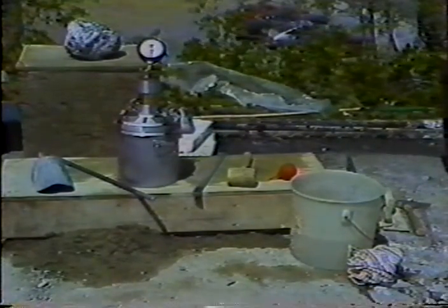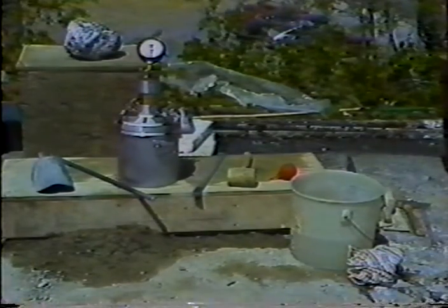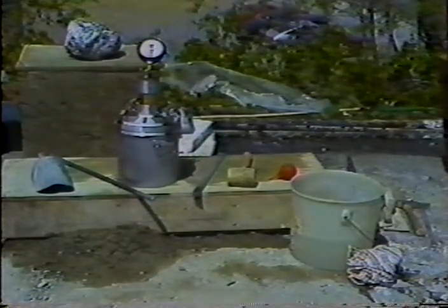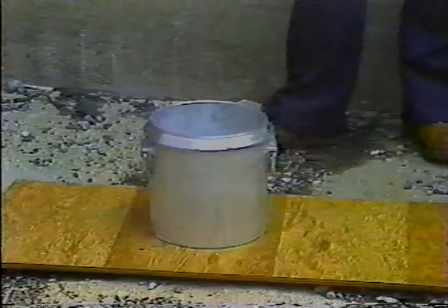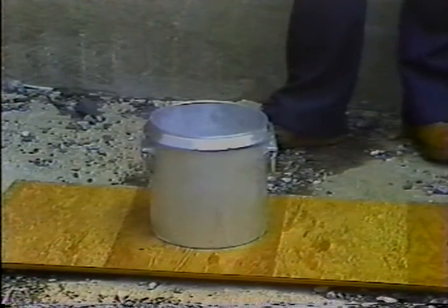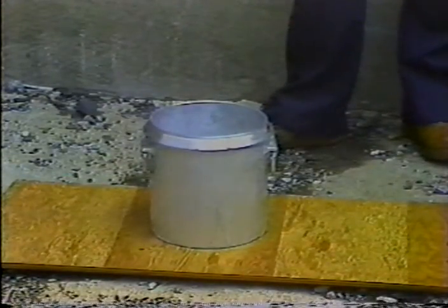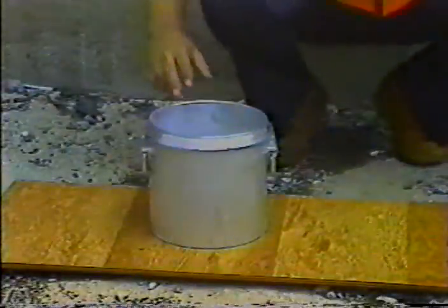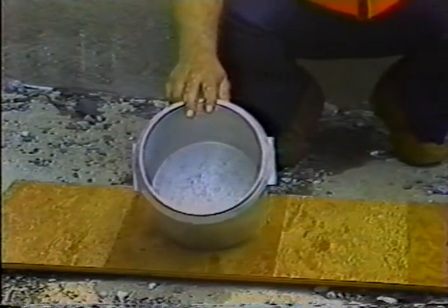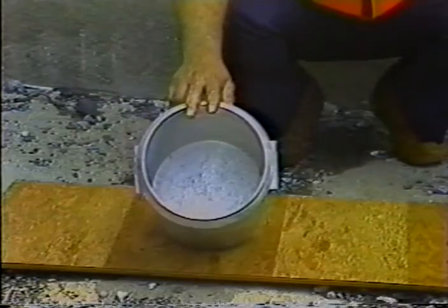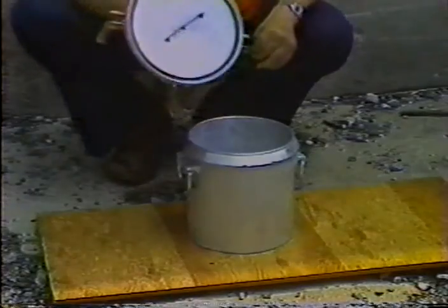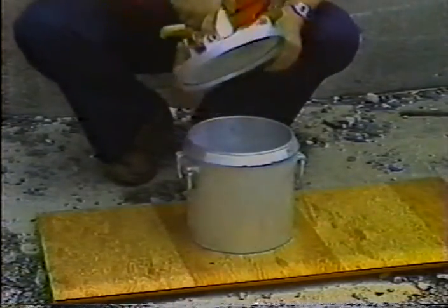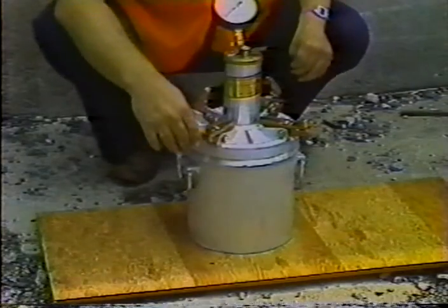Before any concrete is brought to the job site, be sure that all test equipment is on hand and in good condition. And make sure that the work site is ready for the concreting to begin. The pressure meter has a pressure-tight base to hold the concrete sample. Be sure that the base is clean, inside, outer rim, and upper surface of the flange. Remember that any buildup inside the base will alter the volume and void the test results. The cover must have a smooth, clean outer rim and flange surface. When clamped together, the base and cover must be pressure tight.